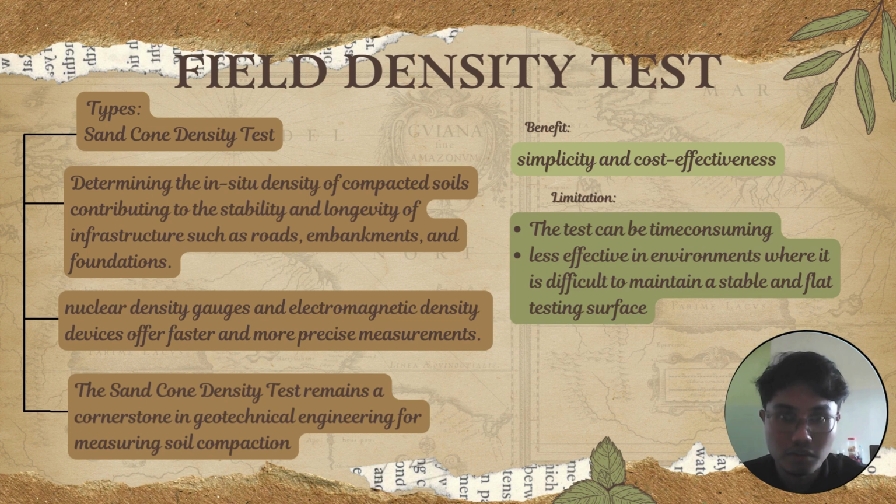I will present about field density test. The type for this test is sand cone density. The main purpose for the test is determining the in situ density of compacted soil, contributing to the stability and longevity of infrastructure such as road, embankment, and foundation.